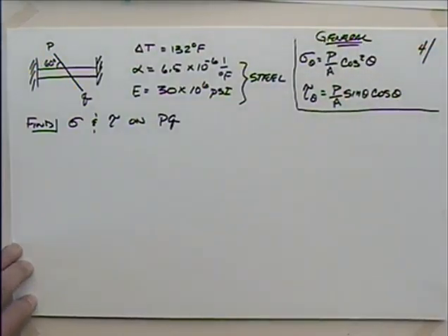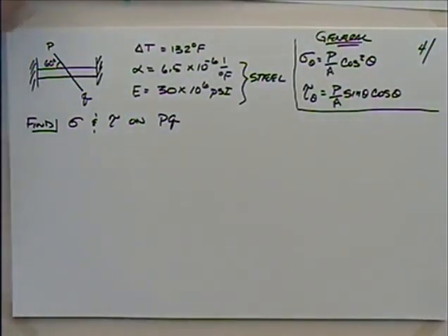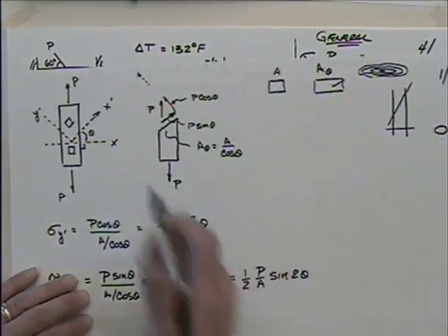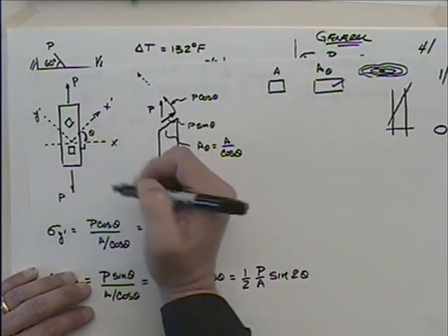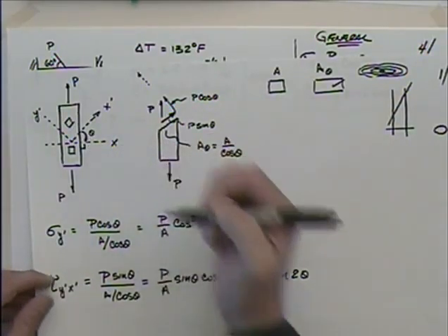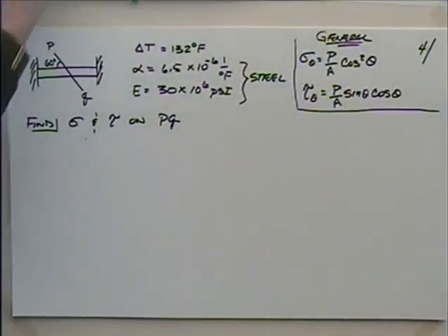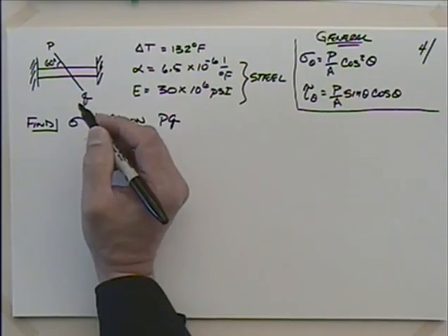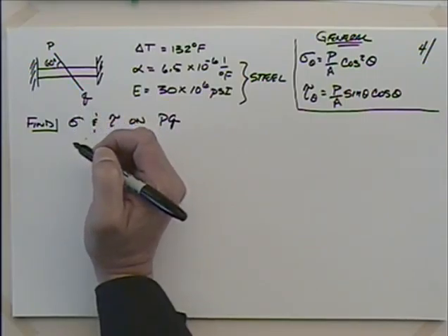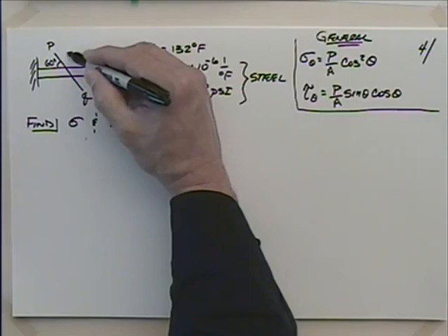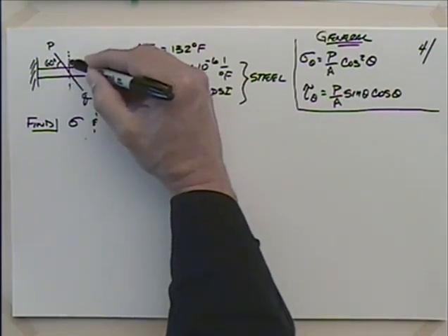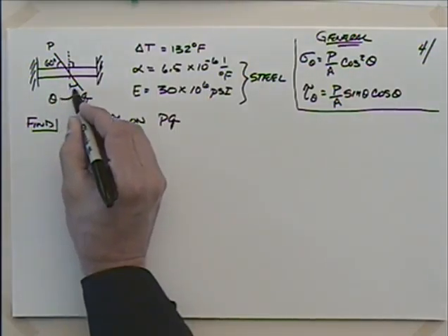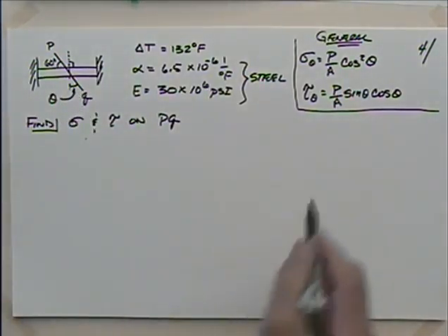Now the one thing we have to be careful of is we've got to go back and look at how that theta was derived. So if we talk about how we started today, the angle was based off of the normal direction, the perpendicular direction. Whereas I've based this angle here off of the axial direction, haven't I? So what's theta going to be in this thing? If I were to put this normal direction in here, this is now theta, isn't it? So what's theta equal to?